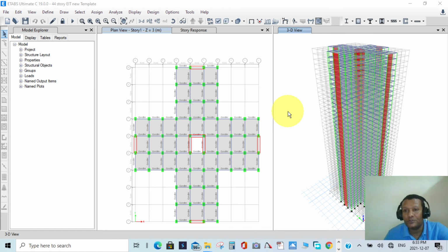By doing so, we decouple the equation of motion for each mode separately. And if we find the response of a structure by calculating each equation of motion for each mode and summing the results, the analysis type is called response history analysis.